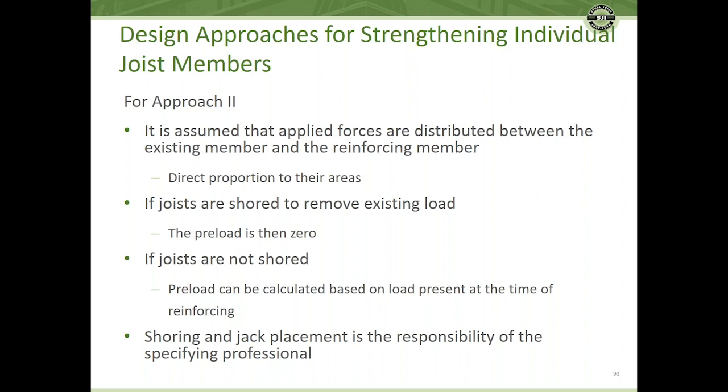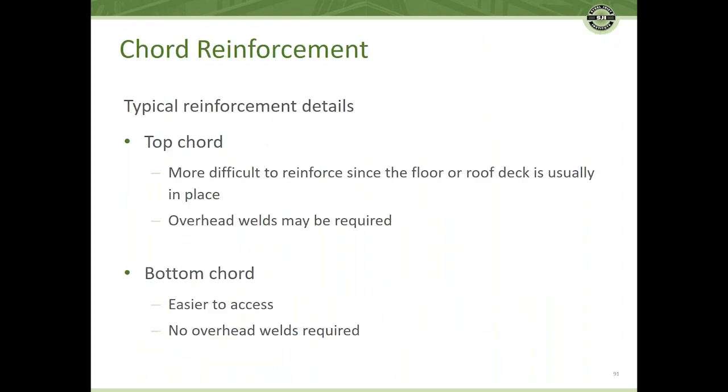And if the joists are not shored, preload can be calculated based on load present at the time of the reinforcing. You know, maybe 50% of the dead load, for example, might be used. And shoring and jack placement is the responsibility of the specifying professional. This is always something that we really need to pay close attention to, because like in that one slide where the end support was removed, we need to make sure that jacking is done appropriately so that the whole building doesn't collapse and possibly cause injury to people.